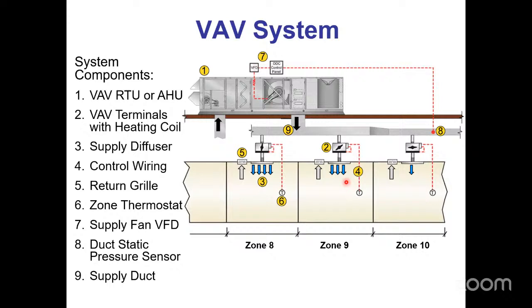If it comes straight down, it's probably going to go on my head, and now as the occupant, I'm going to be pissed off. If you get a diffuser specifically designed for VAV, and Titus and Krueger and all these people have that, then even on low turndown, the diffuser should still have good throw ability. There's actually a rating for that. It's called ADP. That's a whole other hour-long discussion. But you should get a diffuser that's labeled as a VAV diffuser. I'm not talking about VAV where they put a little damper in there. I don't want that. I want a regular diffuser that's designed for VAV systems and has a good ADP throw. So you need those diffusers on there.